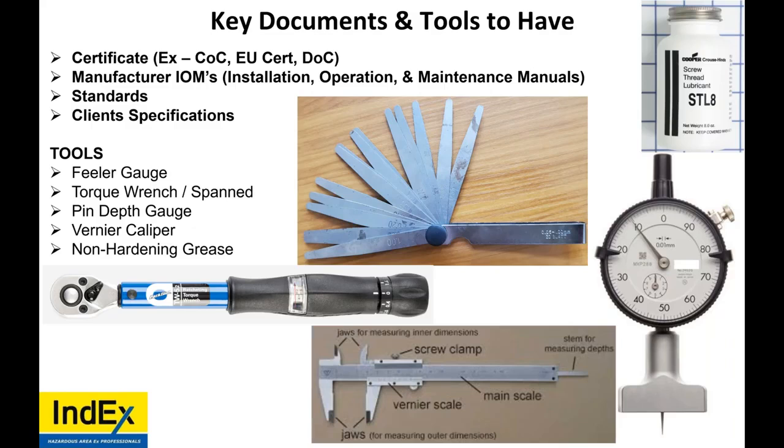If it's explosion proof, that's a different story. But if you're drilling flameproof enclosures on site, you are at significant safety risk, okay? Do not drill flameproof enclosures. We drill cable gland holes for explosion proof on site.